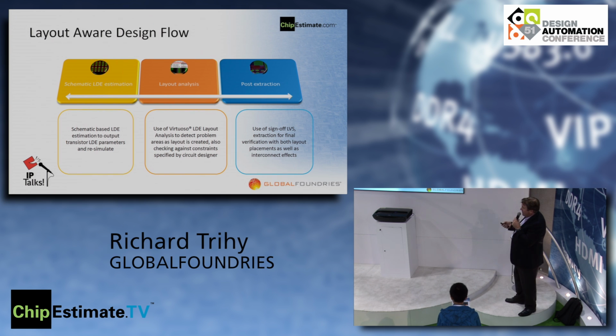And the value of this is that at the schematic level, we have a way to estimate the impact of stress and show it to the designer in the schematic. It's also integrated into Cadence's Virtuoso LDE layout analysis, so in real time, the layout engineer can track the constraints from the designer and make sure he's not exceeding them. And then, of course, for full accurate post-extraction, the same capability is built in there, so you get a fully accurate model of the behavior of the transistor.